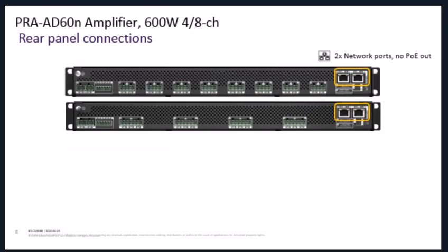Going into the amplifiers, here we have 2 network ports, no PoE output here. And it depends, of course, if you're using 8-channel or 4-channel amplifiers, then we have 8 or 4 loudspeaker outputs here. And then we have a dual 48-volt power connection for each device.